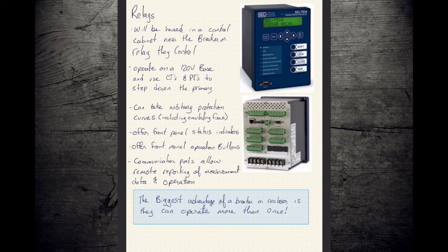So a little more about relays. We're going to focus on just modern relays. We're not going to focus too much on the old electromechanicals. The electromechanicals, you will find them. They're still installed out in the field. Digital relays have been around for almost 30 years now, so you really only find the electromechanicals in some really old stuff or in some hydraulic reclosers, which are a beast unto themselves. I'll touch more on those next week.